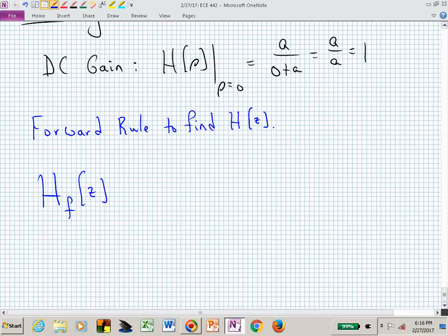That's not the grade that this poor transfer function is receiving. This is just labeling it as a forward numerical integration approach. This is now found from H(s) in what way? We just derived this relationship between s and z, and we said if we replace s everywhere with z minus 1 over capital T, we will have an expression for our low-pass filter.